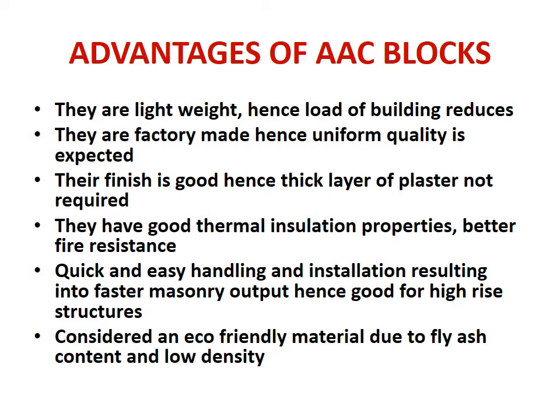Advantages of AAC blocks are that they are very light, and hence the loading of the building reduces because the load of masonry work gets reduced, and therefore the load on beams and columns and foundation also gets reduced. Therefore there is a saving of other materials also. Then they are factory made, so uniformity is there and quality also can be expected. And then their finish is good. There's no rough face, and a thick layer of plaster is not required, which we require in ordinary bricks.